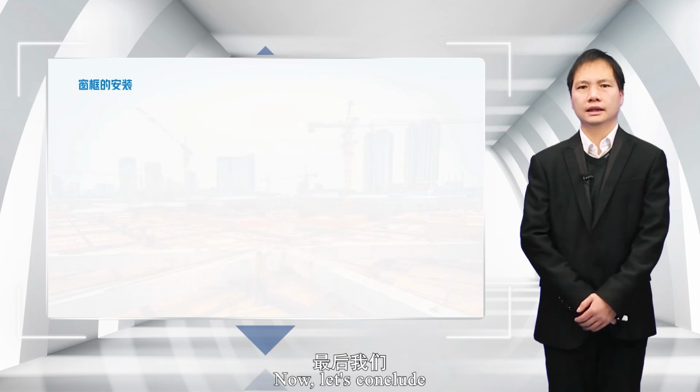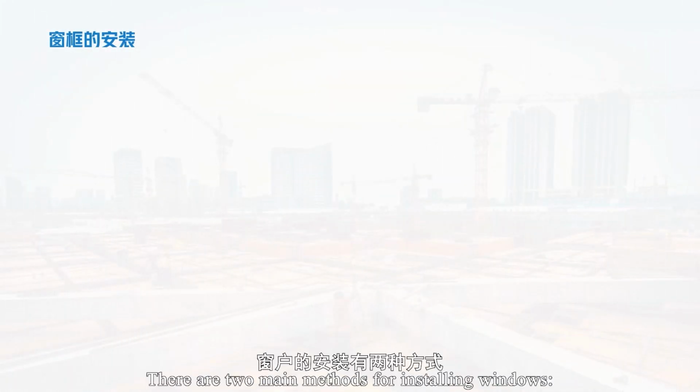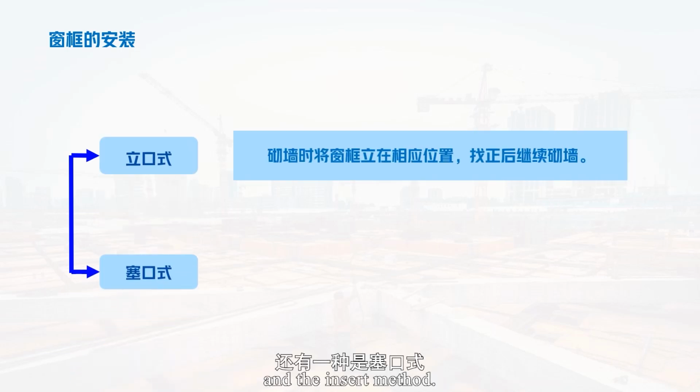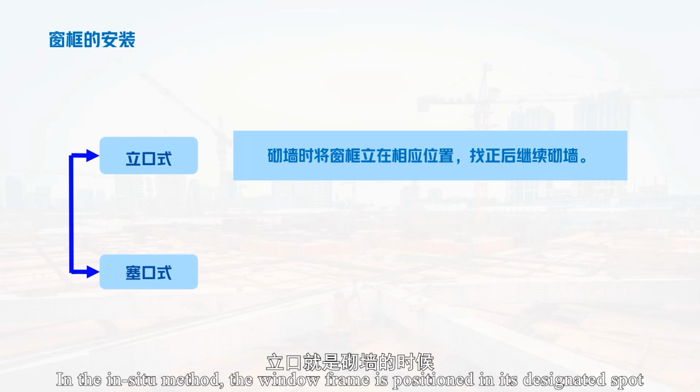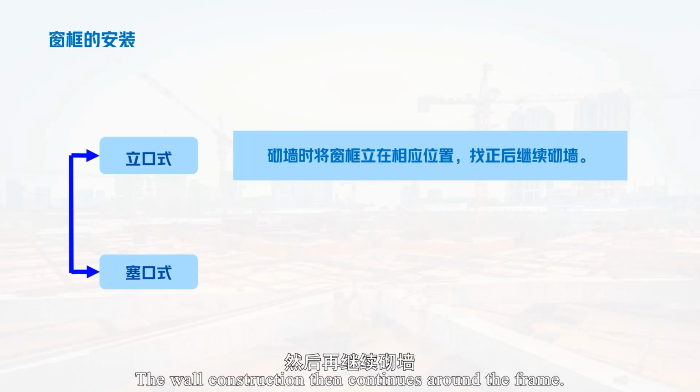Now, let's conclude by introducing the installation of windows. There are two main methods for installing windows: the in situ method and the insert method. In the in situ method, the window frame is positioned in its designated spot during the wall construction process. The wall construction then continues around the frame.